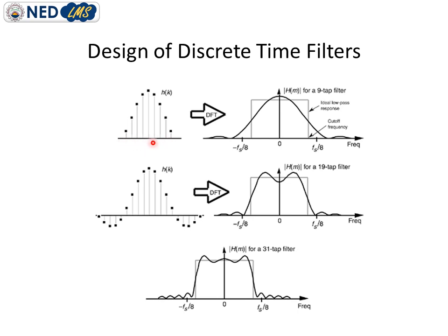Remember, from these coefficients we actually design a filter equation or difference equation, and as you can see the number of coefficients is lesser, so in the difference equation the delay associated with the input is lesser, or the delay blocks utilized in the FIR filter are fewer. So we can say fewer filter coefficients means a less complicated filter design.